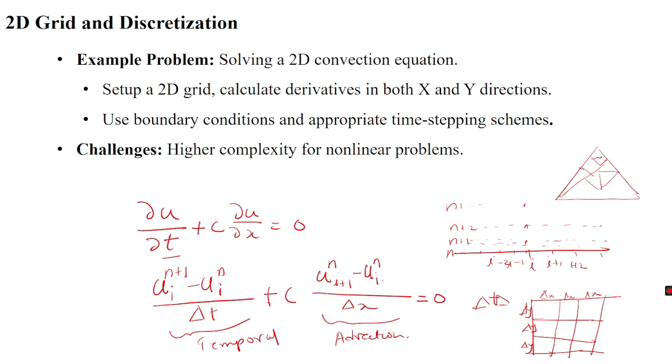So we would apply the boundary condition to the system, for instance setting the velocity to 0 along the wall, or no-slip conditions, and setting up the moving lid on the top. Okay. Now suppose we want to change the cavity shape to something more complicated like a triangular cavity. The equation remains the same, but the grid setup becomes trickier. If you try to discretize with the regular grid, what we have seen for the rectangular or square grid, we will run into some issues, especially at the corners,